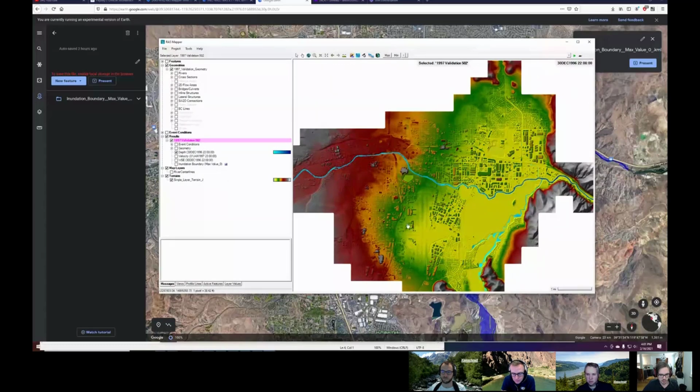For today, we're going to take a look at a terrain and a model from Reno, and I picked Reno because it has all the buildings in the terrain, so it's interesting to look at in 3D. And there's verticality too to the water. If we look at the water surface elevation, that is a big jump, I guess. We're going from 4,500 to 4,300. So there's a difference in water surface elevation there, so you can see in 3D how the water will flow in the Z axis.